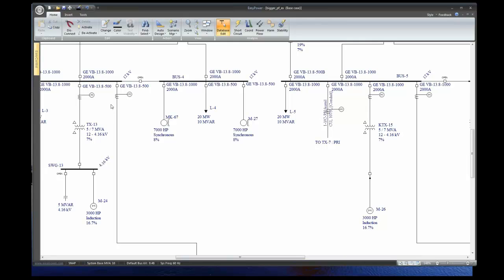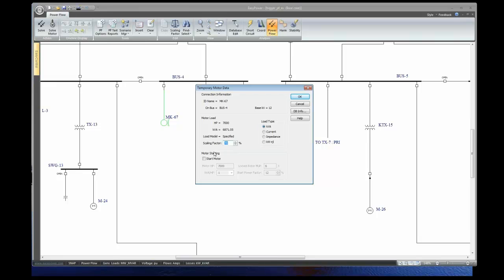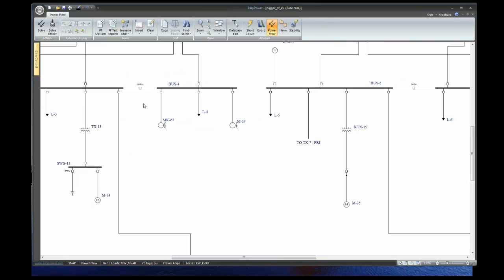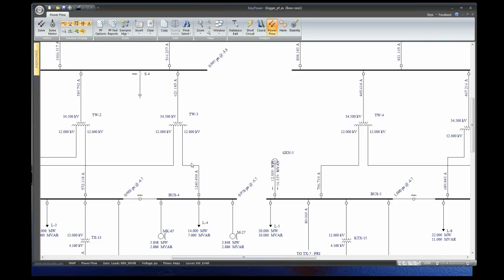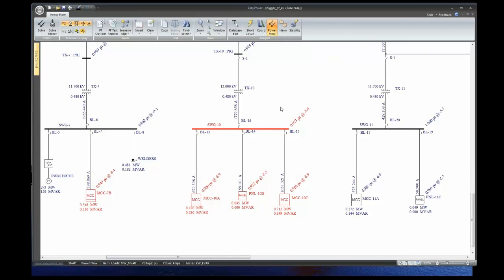All right. So when I'm in Power Flow, I can adjust that scaling factor for any motor or any load as temporary data. But I can also do it as a group. Let me run the Power Flow here real quick. So if I look at this, I see this is turned red because the voltage is low, 0.923. And it says 1800 amps, or 1780 amps.